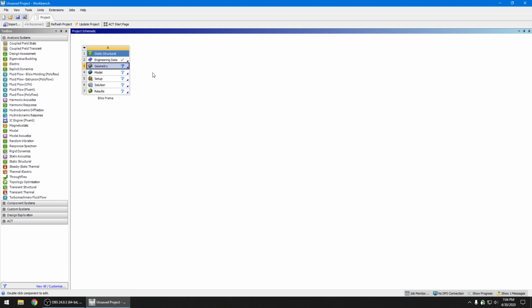And alright, so as we are going through the problem, Ansys, you will find, is very helpful. Things will turn into green check marks if they're correct and good. Not only in this menu, but in all the internal menus as well. So, see, we have a green check mark. That's good. That means it's done. We don't really have to pay attention to that one now. We go to Geometry and double click on it.